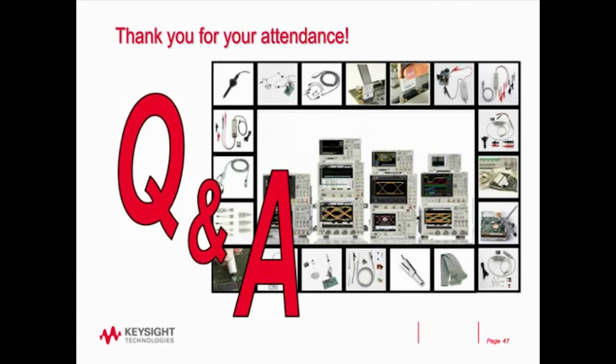Do the input line analysis tools work on the DC input line? I don't think so. If you wanted to measure, you could use the efficiency measurement, which automatically measures DC line input. It'll measure the real power. But you can't use the AC line analysis on a DC input. As for current harmonics, I suppose you could do them, although they should be pretty low.